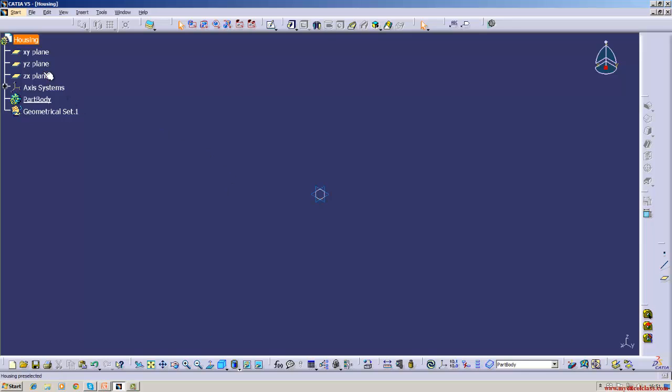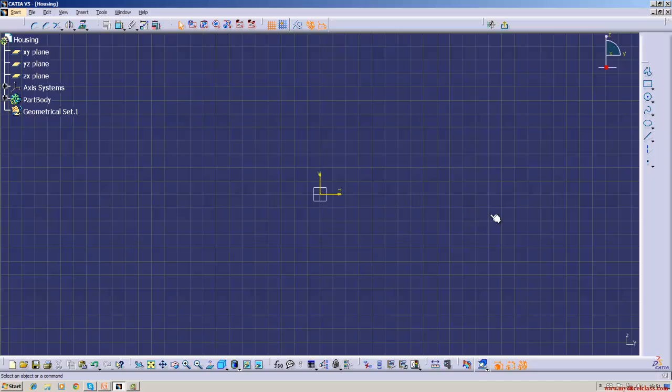What we have to do is first draw a sketch, selecting the sketch plane. XY, YZ, ZX. Any one of the planes we can select. Normally we select the YZ plane, XZ plane also. Depending upon the convenience where you want to place the part, you can select the plane. You will know it later on. Normally they select the YZ plane as the 2D plane. Select it, it is presented as the sketch plane. I told you 100 mm length. Click here, 100 mm. And this length you don't know. Here what we do, in CATIA, you select, this is a drawing shortcut with line.